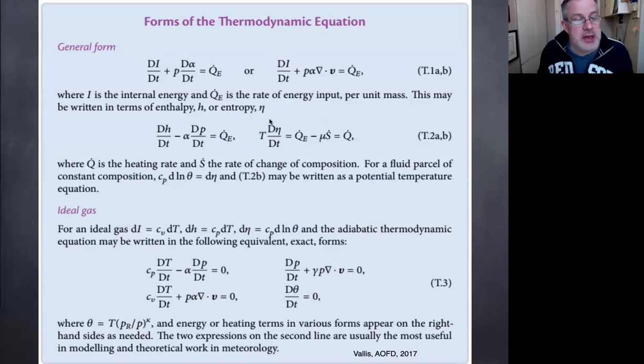But from our perspective, we only need one more thermodynamical equation to close our budget. So if we assume that all of the changes are reversible, that is, the amount of randomness is not changing as the motion flows around, then we can use entropy and energy interchangeably. They both are expressing the same thing about how the fluid evolves. This form looks even the simplest of all. It doesn't have a compression term, except it has this multiplier by temperature, which does make things a little bit complicated.